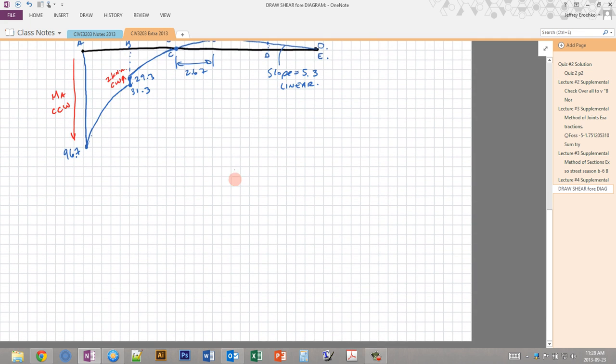Now as a final step, let's try to draw the displaced shape of this system. This is pretty straightforward to do when you actually know the moment diagram. So we have our wall. Okay, and now let's just draw our undisplaced, our undeformed shape here, which just goes all the way to here. And this is where we have our roller.